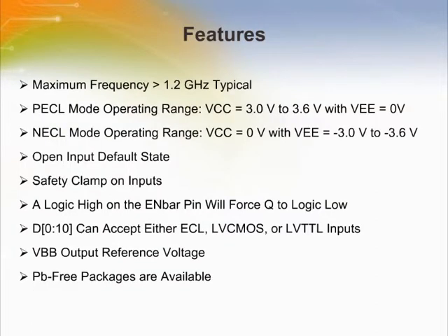The MC100EP196 is a programmable delay chip designed primarily for clock deskewing and timing adjustments. Programmably, it provides variable delay of differential ECL input signals. The EP196 has similar architecture to the EP195, with the added feature of further tunability in delay using the FTUNE pin. The FTUNE input takes an analog voltage from VCC to VEE to fine-tune the output delay from 0 to 60 picoseconds.